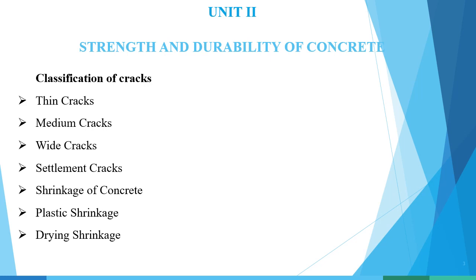In such a situation, the following measures could be taken to reduce or eliminate plastic shrinkage cracks. Moisten the subgrade and formwork. Erect temporary wind breakers to reduce wind velocity over concrete. Erect a temporary roof to protect green concrete from the hot sun. Reduce the time between placing and finishing if there is delay. Cover the concrete with a polyethylene sheet. Minimize evaporation by covering concrete with burlap, fog spray and curing compounds.